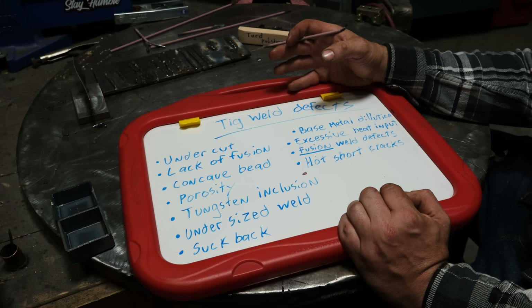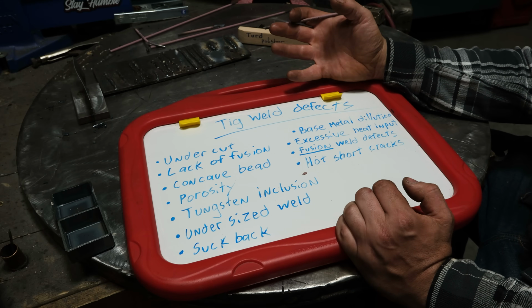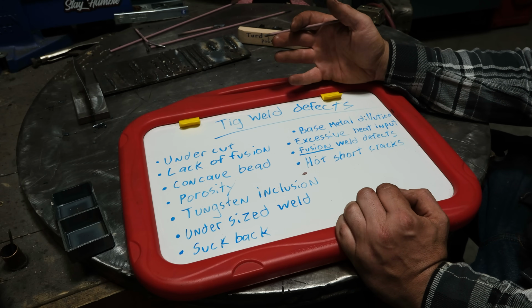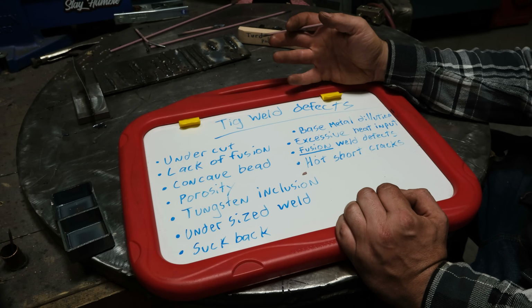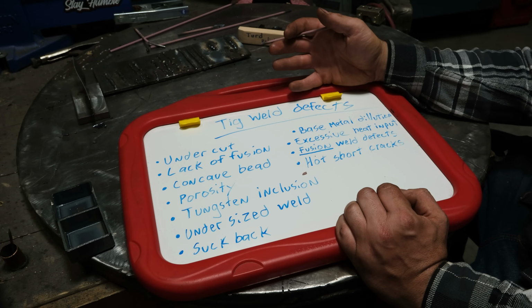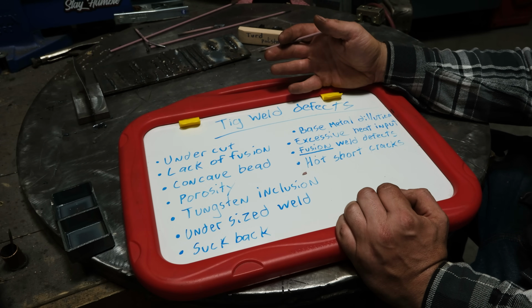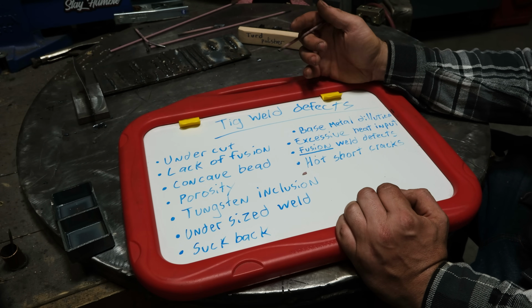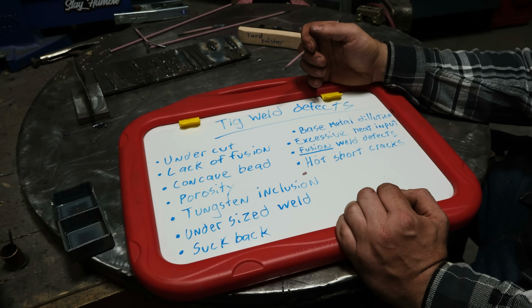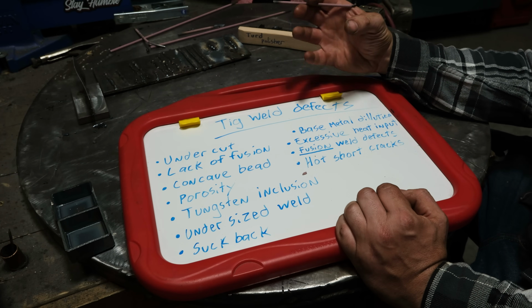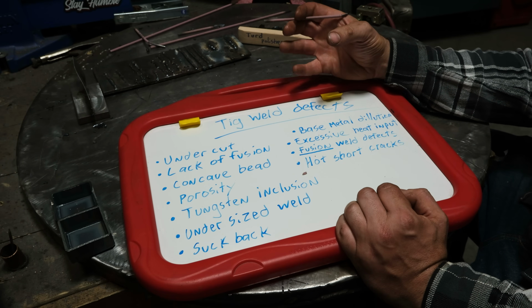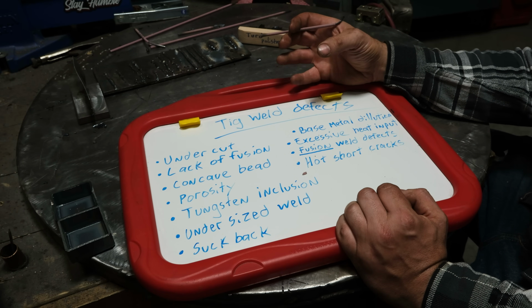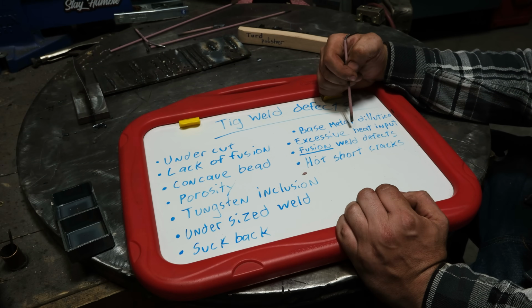The only exception to that, and well, there's probably tons of exceptions, but in some cases that may be acceptable, like on say chromoly, if the part is being heat treated after it's welded. Since I don't think you have a heat treat oven, nor are you probably heat treating anything after you're welding it, avoid doing it. Push enough filler, always have enough dilution of that base material with filler, and don't just dilute the base material only. That's bad.